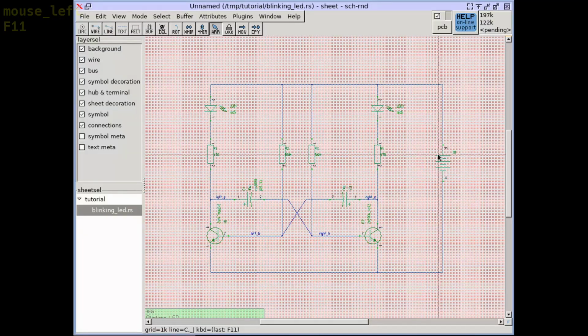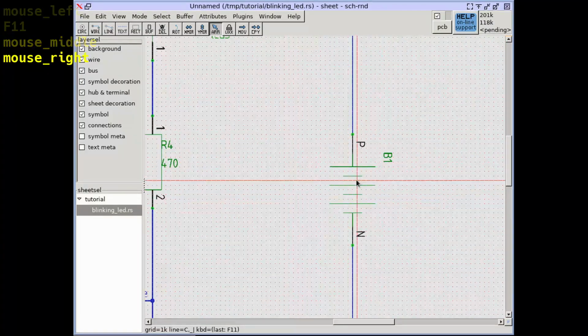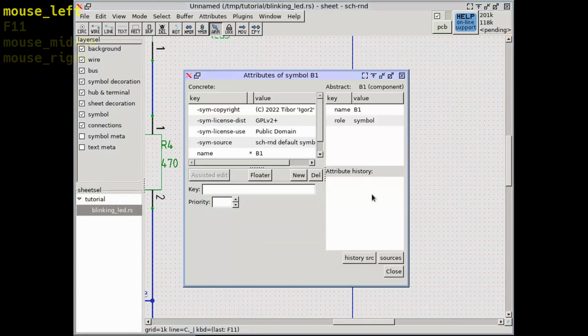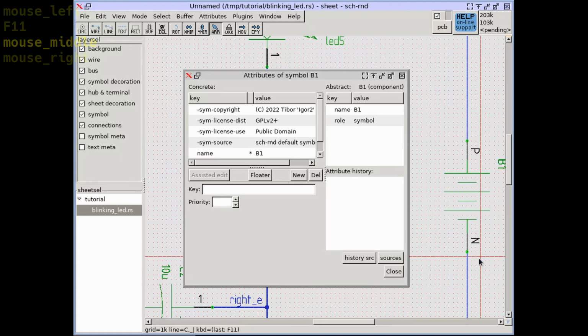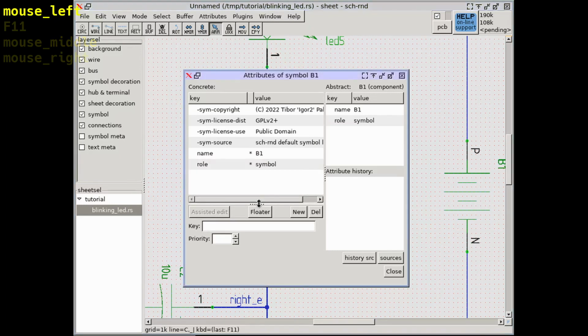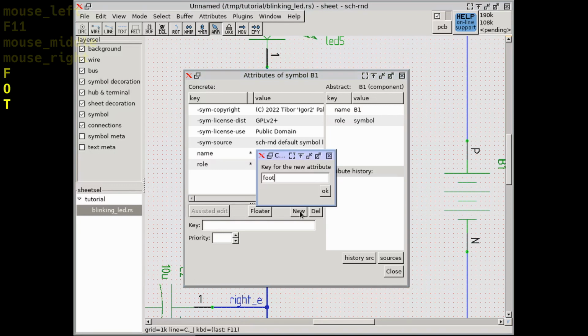There is one symbol we did not handle. The battery. It is a special case, because we want to have it on a generic connector footprint, but it is a polarised part with P and N for terminal names. The easiest way to handle this is a custom port map. Details will be covered in a subsequent video.